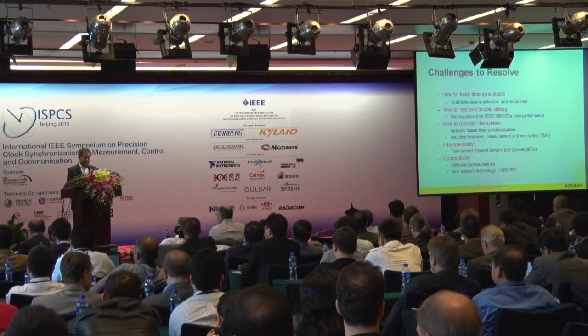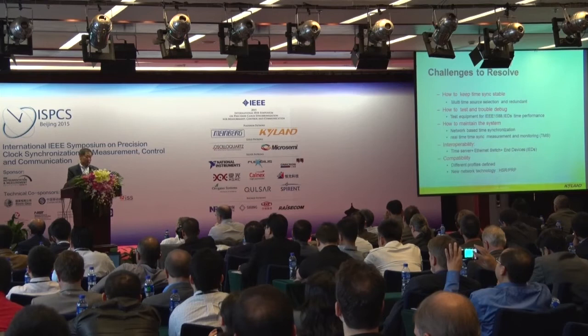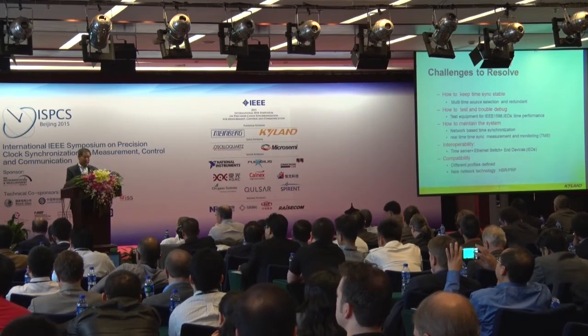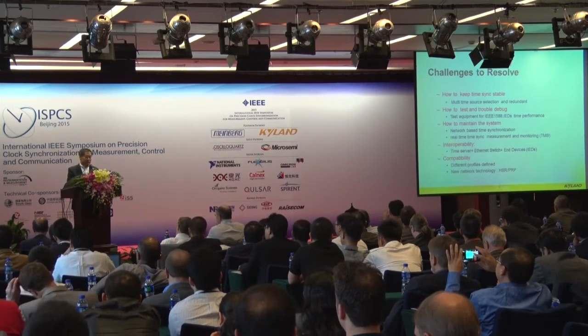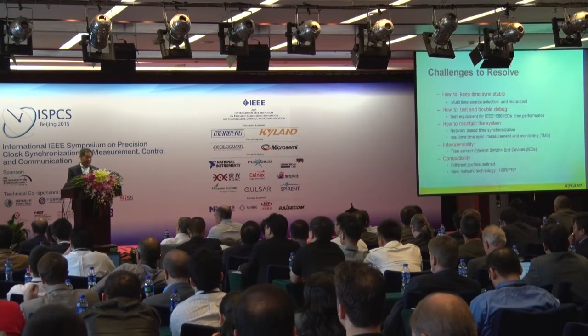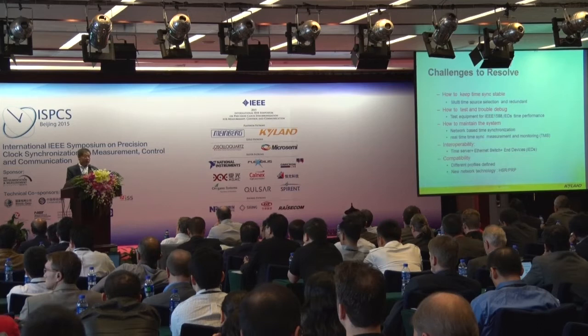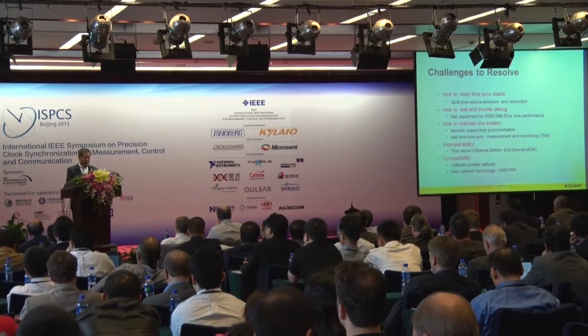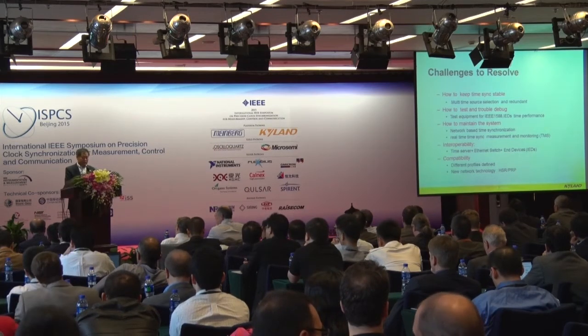Second, we have equipment to test the time accuracy, especially the IED's time performance. We not only test the clock, such as IEEE 1588, but we also measure the time delay of Ethernet packet transmission. So this is more work in the substation.